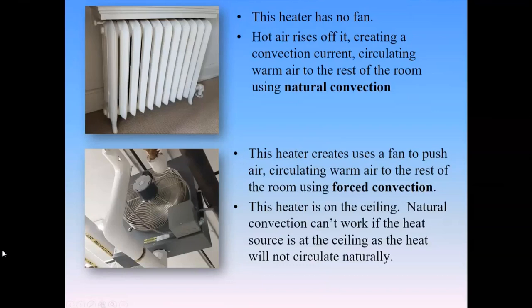And if we want this heat to move around to a larger area than just what's being set up with our natural convection, we can use the fan to force a much larger area that heat is making its way to. The other thing with the forced convection, because it generally can absorb much more heat or exchange much more heat, we can get away with a smaller heat exchanger to be able to exchange the same amount of heat if we have that fan pushing air through.